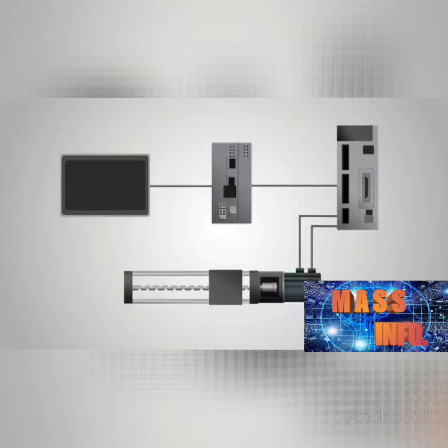The servo motor utilizes a regular motor and couples it with a sensor for positional feedback. The controller is the most important part of the servo motor, designed and used specifically for this purpose. The servo motor is a closed-loop mechanism that incorporates positional feedback in order to control the rotational or linear speed and position. The motor is controlled with an electric signal, either analog or digital, which determines the amount of movement, which represents the final command position for the shaft.